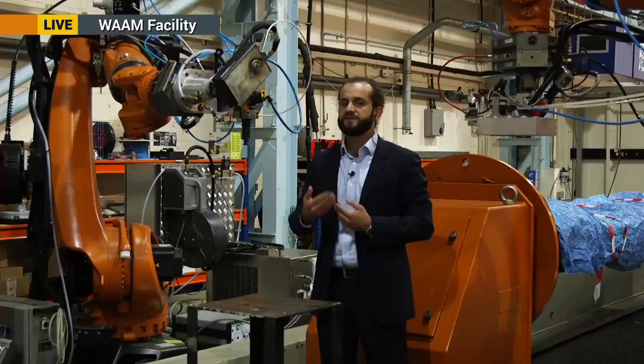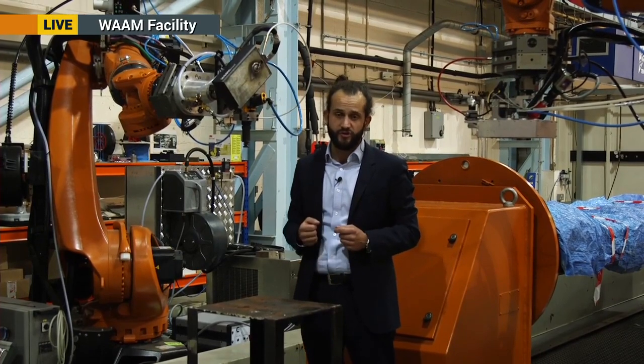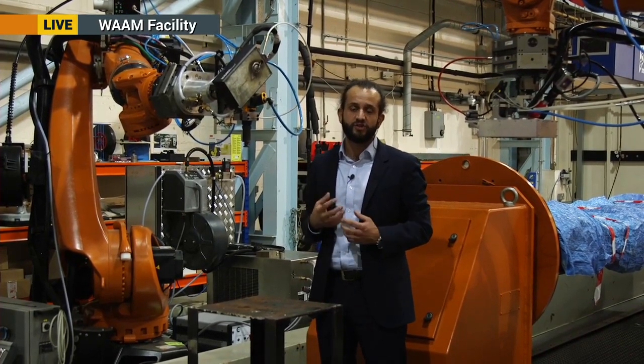In the interim, one of the things that we are doing here at Cranfield is to combine the additive processing with a mechanical treatment, in this particular case using a machine hammer peening process. And what we do with this machine is introducing strain and stored energy in the crystals of the material which has just solidified, just like you would do in a forging operation. And then the subsequent heat provided by the deposition will trigger a change in microstructure.